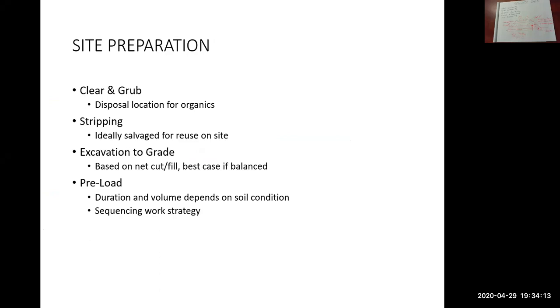So stripping, we just talked about excavating to grade. So preload is the next bullet there. What's the purpose of preload? So you preload a road surface, or a future road surface, I should say, in order to squeeze the water out from down below.